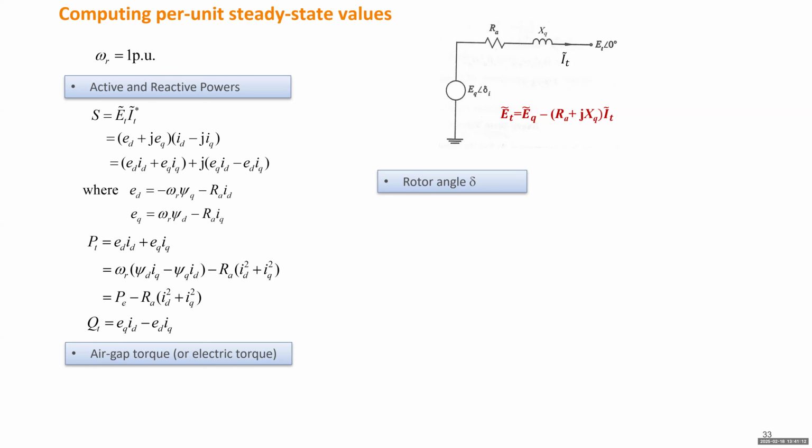So this is exactly the definition of the vector product. If you have a voltage vector with ED, EQ as components, and another vector with ID, IQ as components, the wedge product, which is basically the value of the cross product, will be equal to QT. So the meaning of QT is really just the wedge product of the voltage and current vectors.